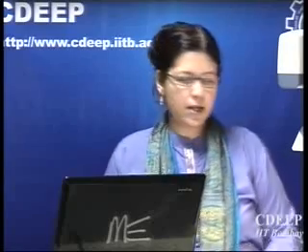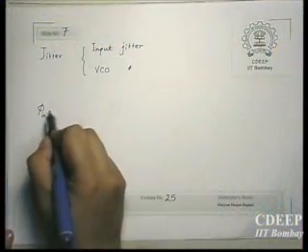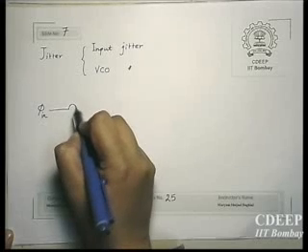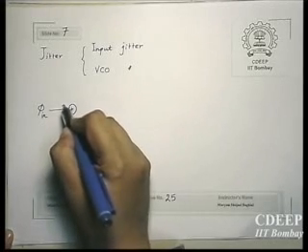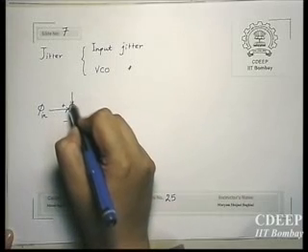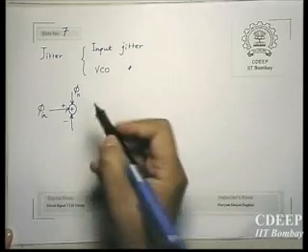But if you have some kind of random variation of this phase, then you can just add it to your phase. That's why the best way to model it, for example, if you have input jitter, this is your phi in, right? You just add your phase noise over here. That's enough.